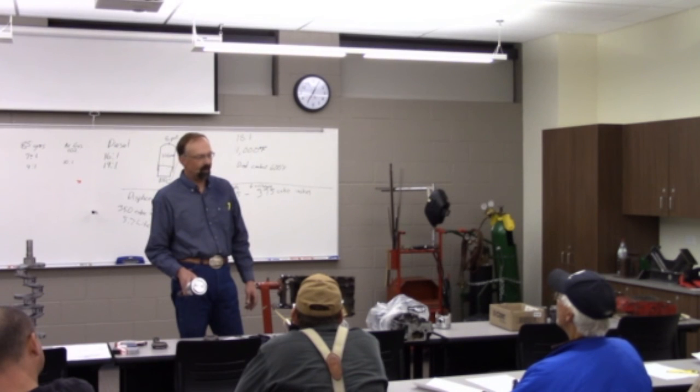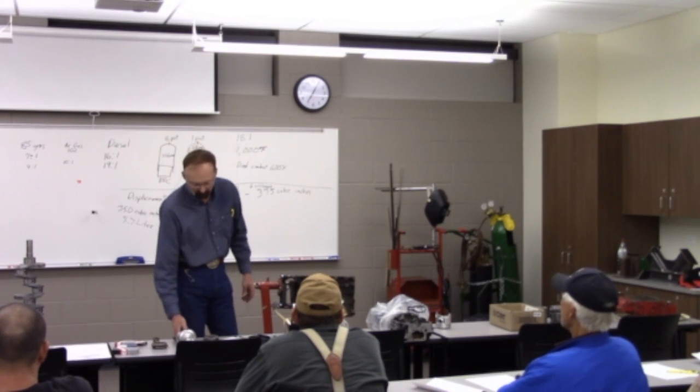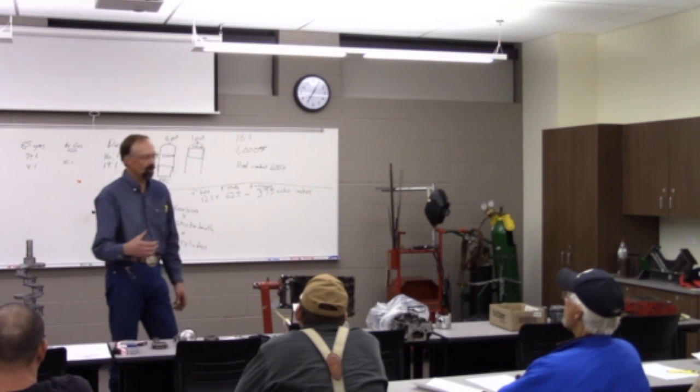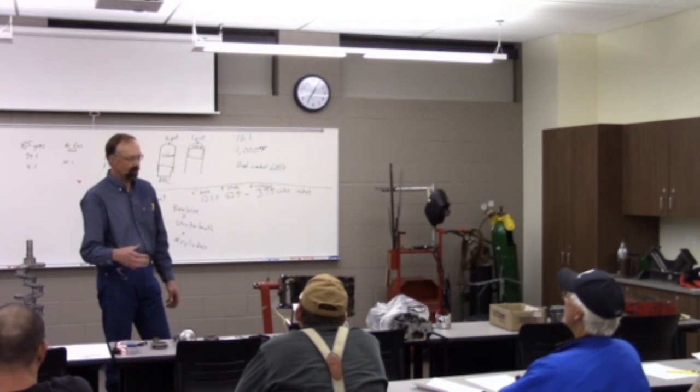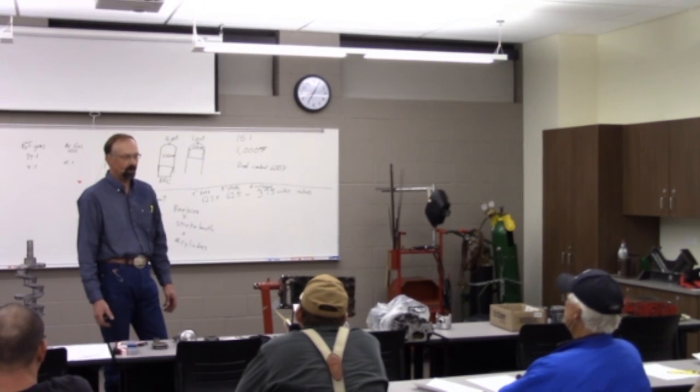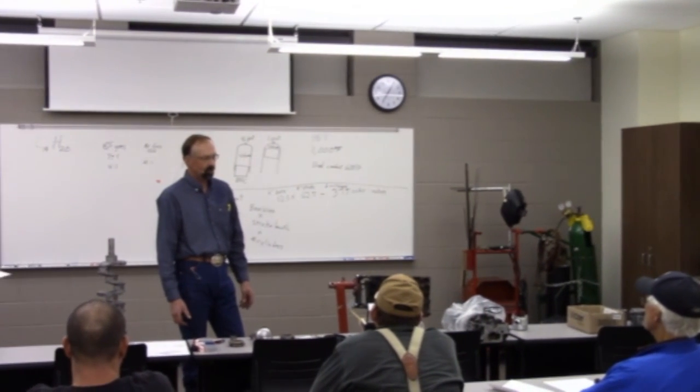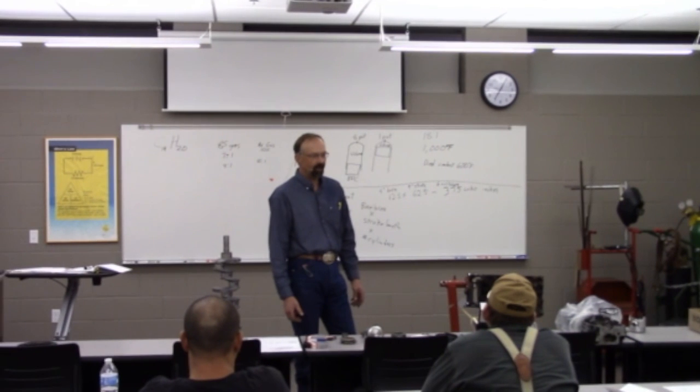And getting that fuel mixture more correct, so we were making less carbon, really seemed to make a lot of difference in how long they lasted. Now, since then, we've also seen a lot of advancements in metallurgy and how they alloy the materials, and I think that's added to it as well.